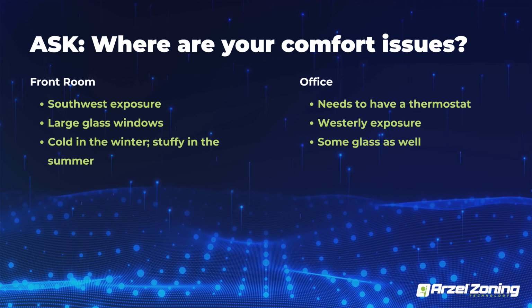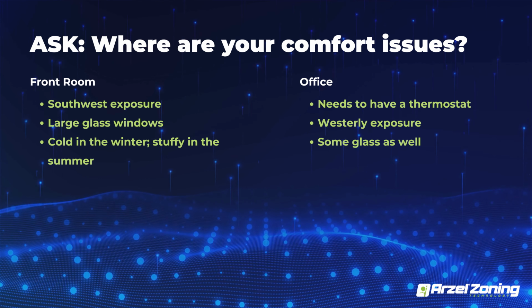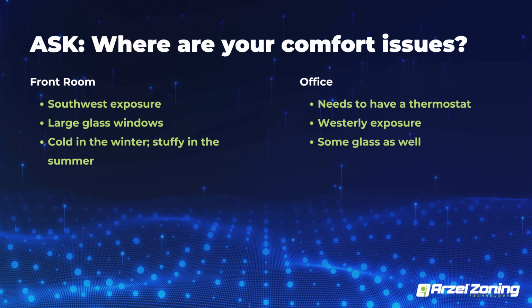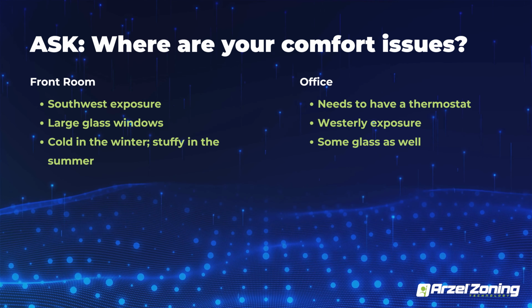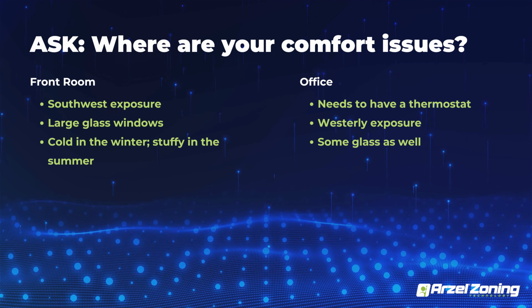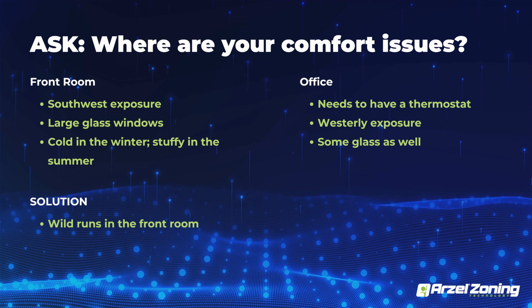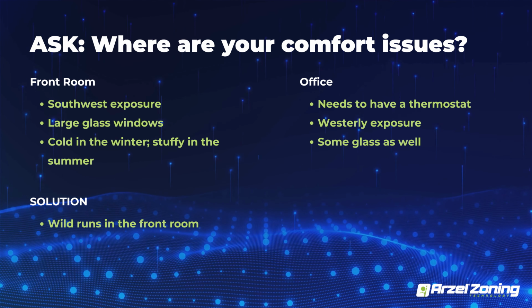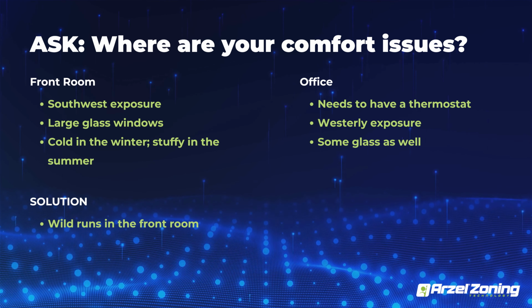I thought then full circle coming into the customer's home, this is the worst area of my house. It's terrible all winter. It's terrible all summer. That particular area of the house, and I'm going off memory, I think it had like 2 7s up high and 2 7s down low. We never dampened them. We left them as wild runs. What we created was anytime the AC called over here, that front foyer and all that glass got air conditioning.